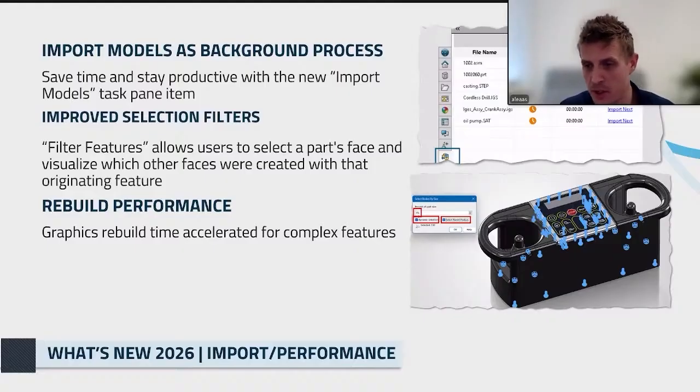There are a lot of nuts and bolts within this STEP file, and when opening the component, we will be able to deselect all of these components, which will then eventually lead to there not being a lot of information that needs to be imported into SolidWorks, and it'll make the import process very smooth.